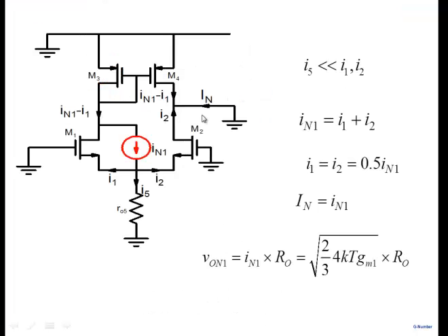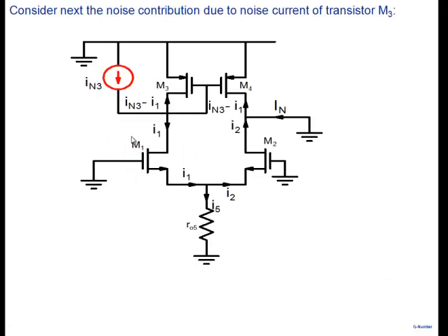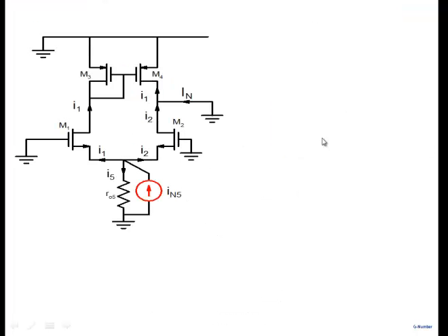Similarly, you go here, this was there on this side, it's not there on this side. This is a differential signal, and differential signals have an impact. This one is a common mode signal here. And remember, the property of a differential amplifier is that anything which is differential is amplified or sensitive. Anything which is common is rejected. So it will get rejected here. Let's see. Now I'm sure you can see what will happen: this current is there. What will happen?